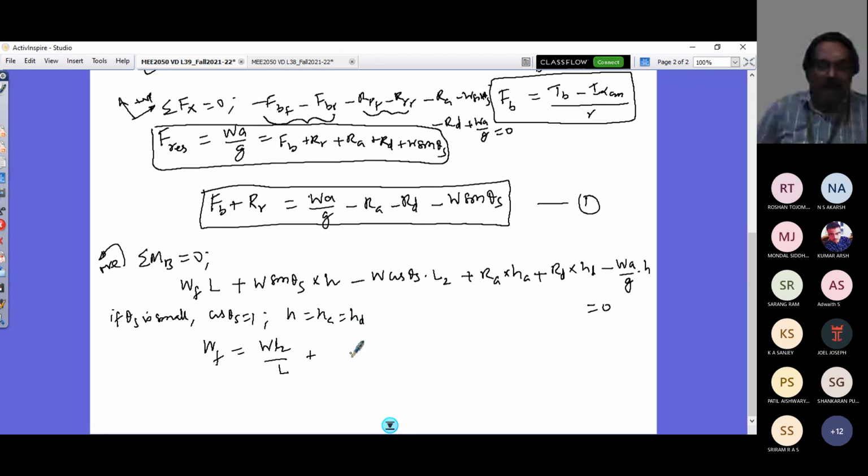Then I would have in this, drawbar resistance I can neglect as in my free body diagram. I don't tow any of the vehicles, so I don't consider this moment, and the rest of these 5 terms would result into this. Since these 3 other resistances are at the same height H, then H by L into, I would have inside the bracket.